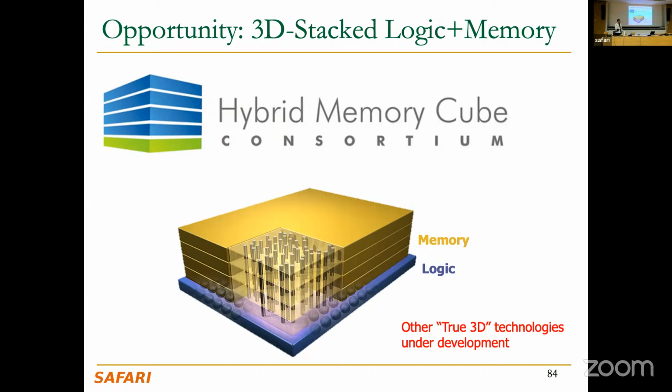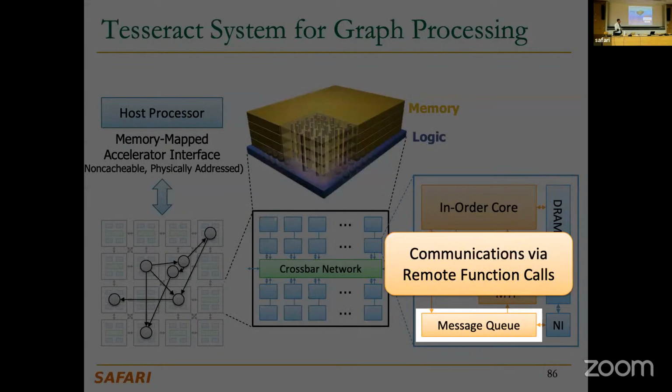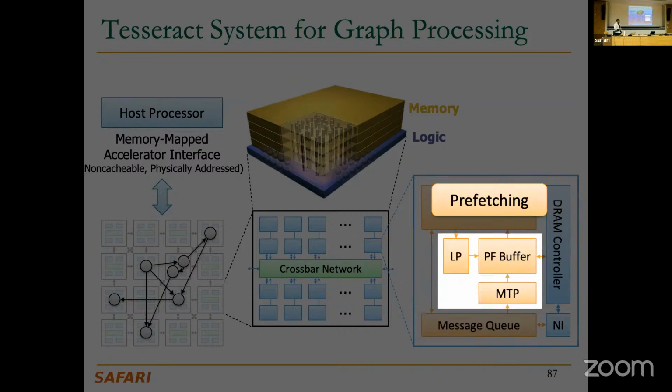By using through-silicon vias over here, we can manufacture them in their own processes and then stack them together. Using these 3D-stacked memories and this logic layer, we designed a graph processing engine inside the memory device itself called Tesseract, which basically is really lightweight cores, all connected in a network topology. And we designed the software stack and the programming abstraction from scratch to enable efficient data processing and data fetching of those graphs inside this near-memory architecture solution.